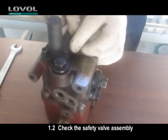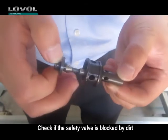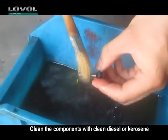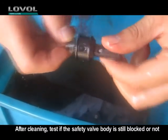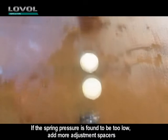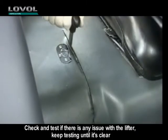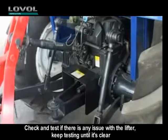1.2 Check the safety valve assembly. Place the components in order. Check if the safety valve is blocked by dirt. If yes, clean the components with clean diesel or kerosene. After cleaning, test if the safety valve body is still blocked or not. If the spring pressure is found to be too low, add more adjustment spacers. Increase the opening pressure of the safety valve. Check and test if there is any issue with the lifter. Keep testing until it's clear.